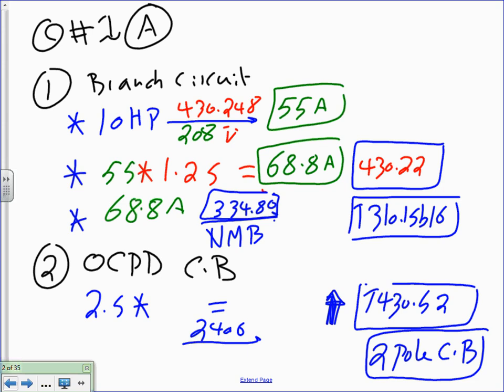60. Why? Because it's an NM cable. It forces you to go to 60. Otherwise, I go to 75. Next quarter, I'm going to throw at you an MC cable. You go 75. That's the only difference. Okay. Anybody two agree on one answer?